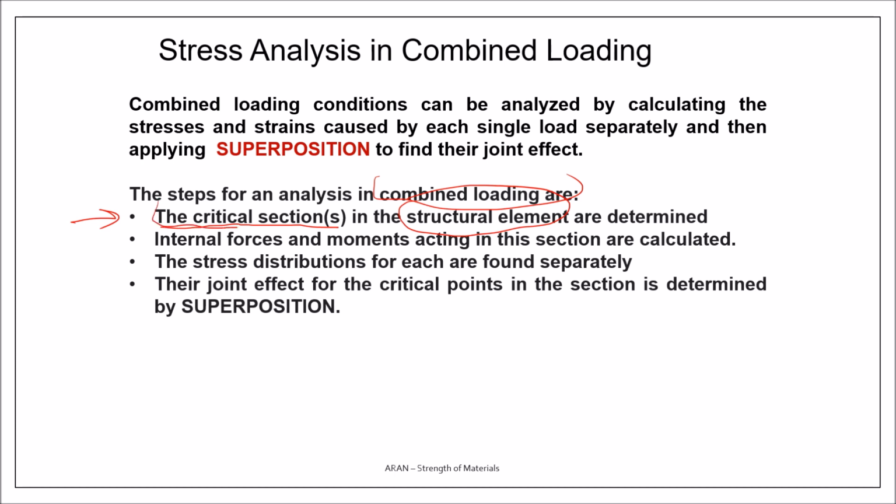For this, we can use the shear force diagrams and bending moment diagrams, and these diagrams show me in which sections the loadings are maximum. If we have the internal forces and moments acting in this section, the second step is to find the stress distribution for each of these loadings separately.